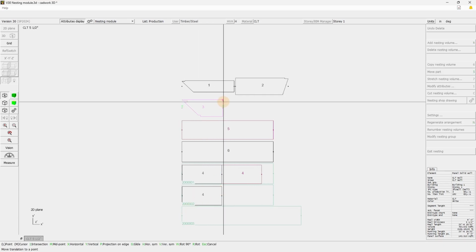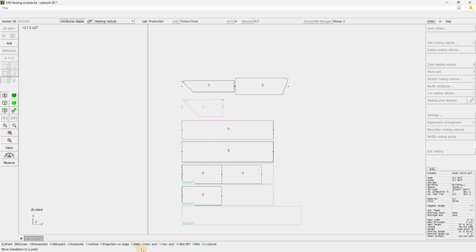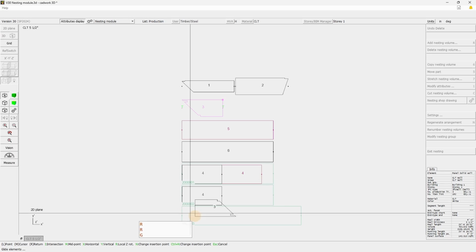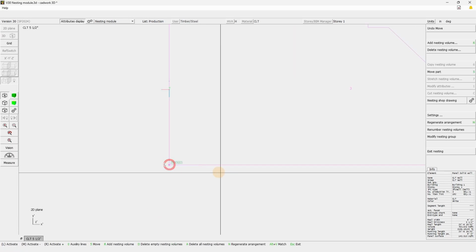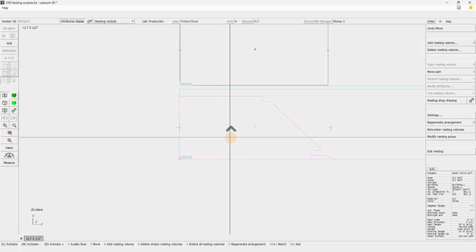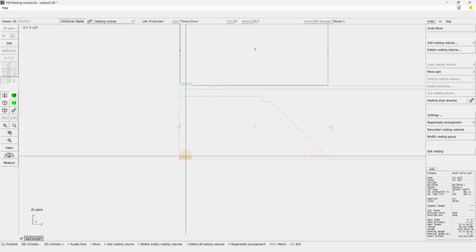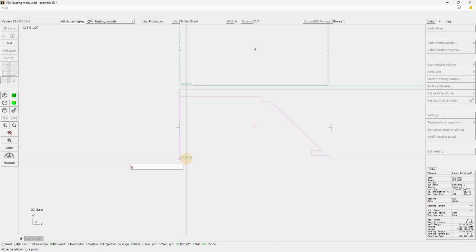If you want a more visual transformation, simply use the glide command with G, and here you can actually rotate and place the element as you'd like. So here, now I could do a 1 inch on either side. So here I can do 5 X, Y, and 5 Y, 1 pretty easily.